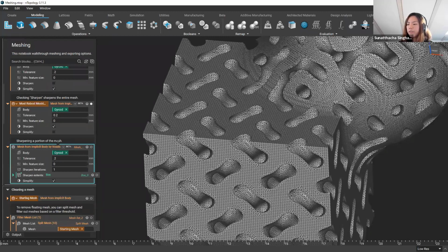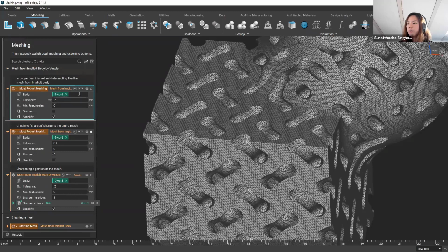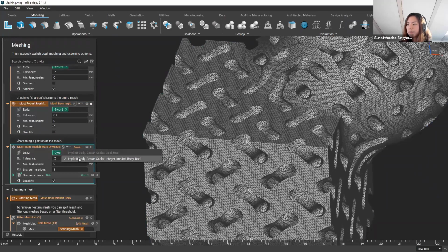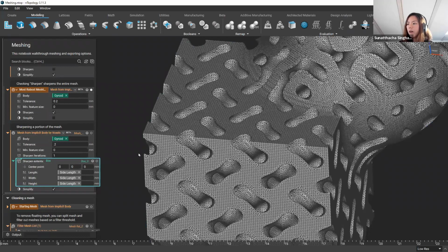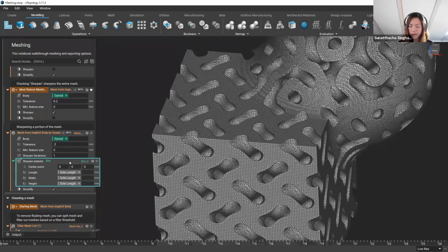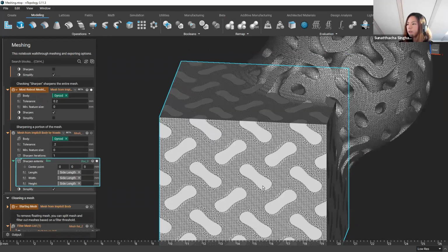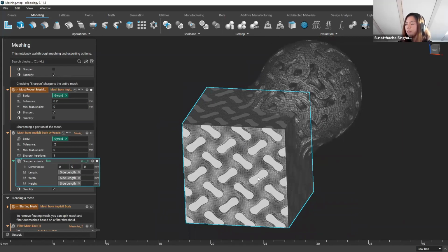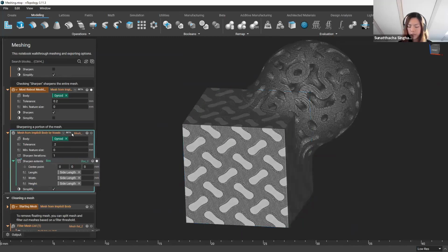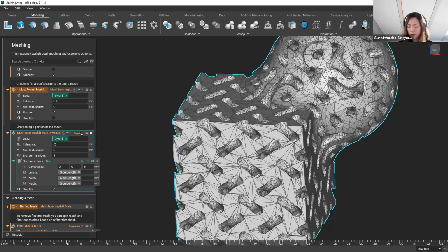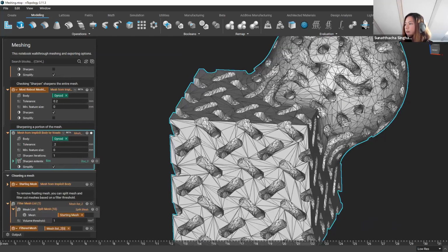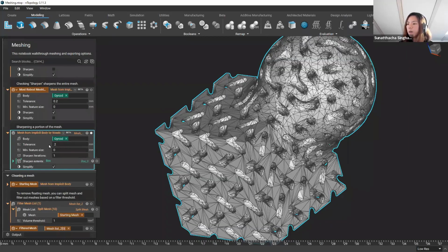And it is also possible with this block if you change the overload and choose the second option. So with these two examples, they're with the first overload. But if you choose the second overload for this block, you have the option of then also specifying a specific portion of your mesh that you want to sharpen. So here we have a box where we placed here right at the part where we have the same cube geometry. And we're saying that we want only this part to be sharpened. And if we isolate this, it is also sharpening just that part instead of everything. So that's an option.